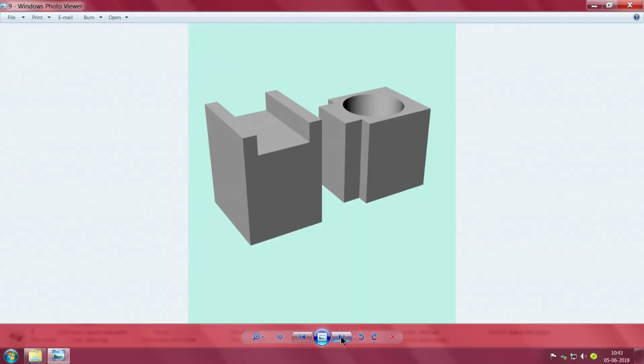Can you see here? Underneath there is a bore and there is something here. While it looks convenient, on further examination I found out that this bore should have been through, then only it makes sense. Now building this, the layers will build up automatically, building here also will build, but to support this topmost structure again there will be a support required like this. So what to do?